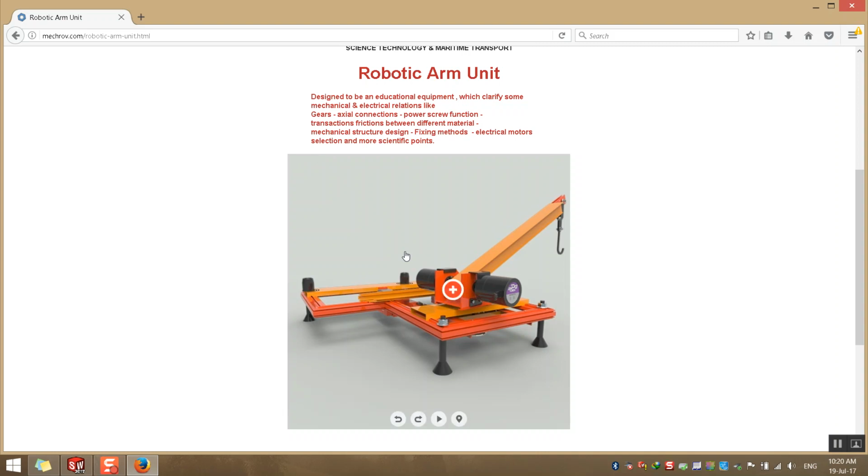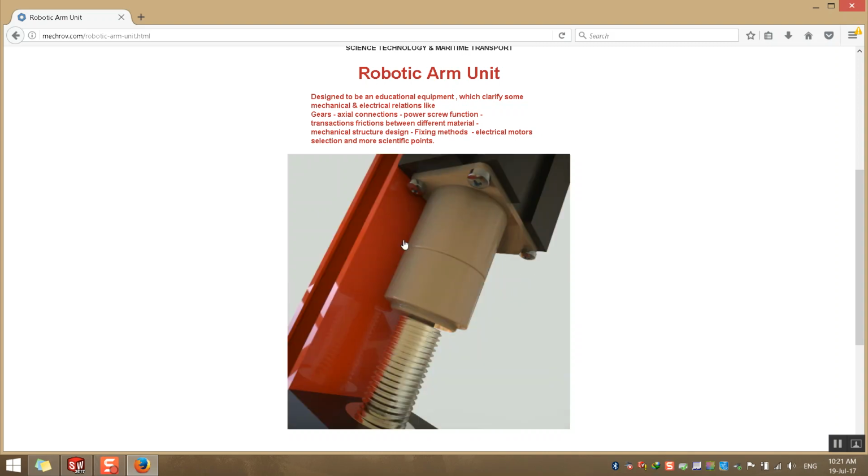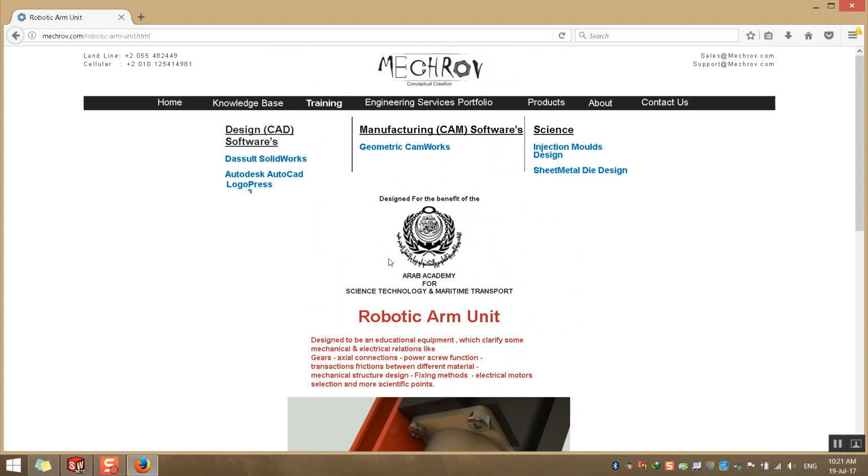It has two icons in SolidWorks. When you model your assembly in SolidWorks, you just click on the icon. It will automatically open KeyShot, import the model and create a link between them. So any change you make here will be updated on the other side. See? This render is a KeyShot render, and this model has been designed in SolidWorks.